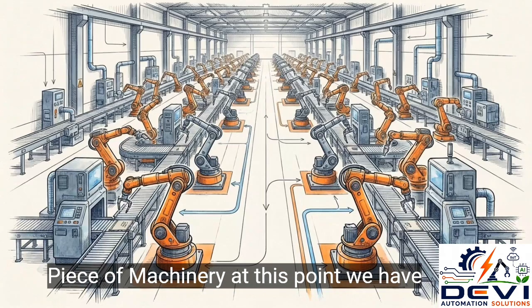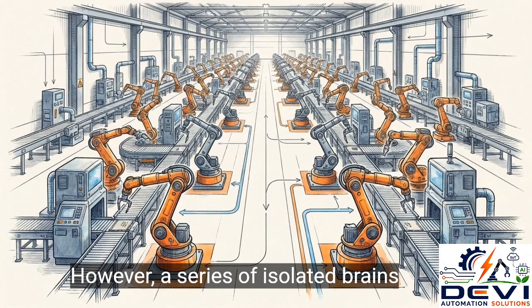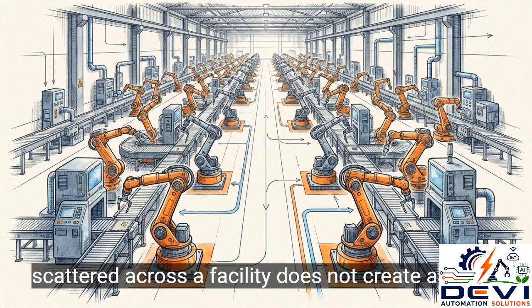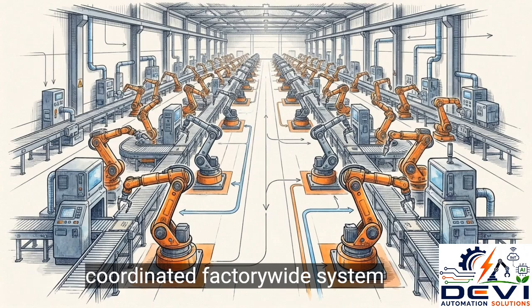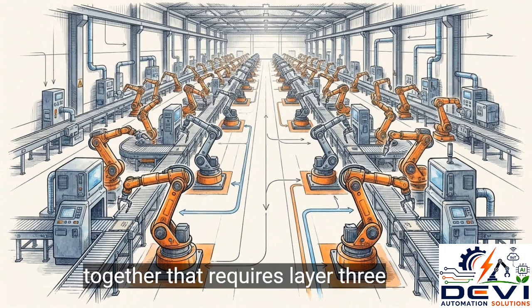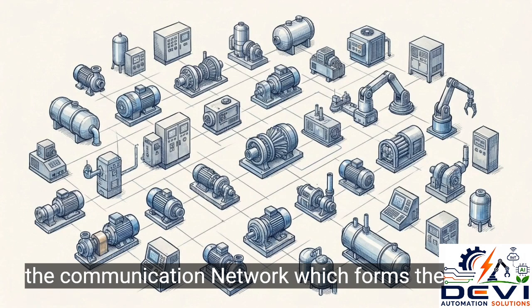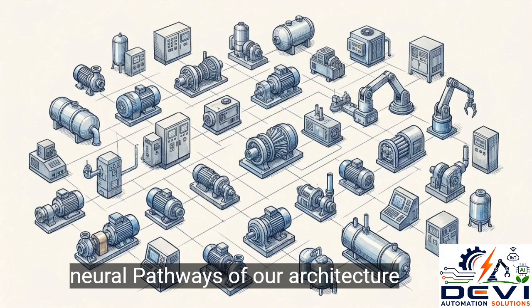At this point, we have local control established at the machine level. However, a series of isolated brains scattered across a facility does not create a coordinated factory-wide system. To monitor an entire plant, we have to solve the problem of connecting hundreds of these isolated PLCs together. That requires Layer 3, the communication network, which forms the neural pathways of our architecture.